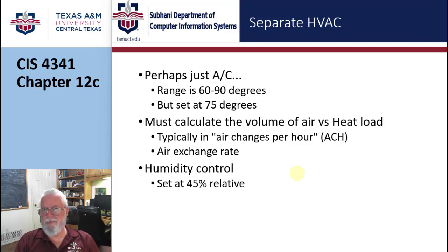All of it, 100%. So 800 watts. I know exactly how much heat is going to be punching out of this thing. Typically you calculate this with air changes per hour, ACH, and some sort of exchange rate. You don't want to have the exact same air being blown over and over. You want some fresh air to come in, all that kind of good stuff.